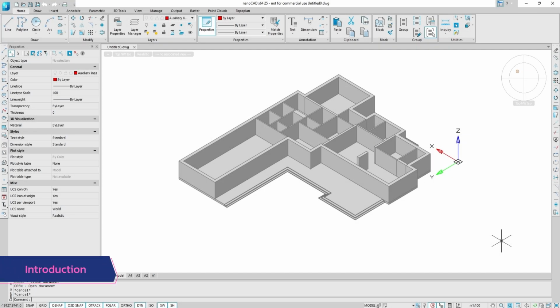Now we can start modeling the second floor. We could create exactly the same floor by copying all the elements, but I still suggest making an additional outdoor veranda. I suggest you recall all the actions that we performed when modeling the first floor. Initially, we placed a raster for convenient modeling. Then we placed the axes. After that, we started modeling the exterior walls, interior partitions and floors. We will repeat all these steps.